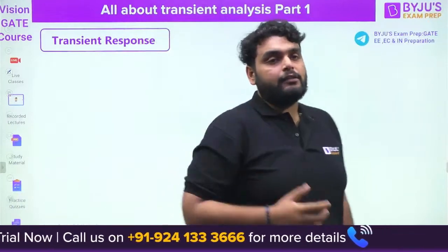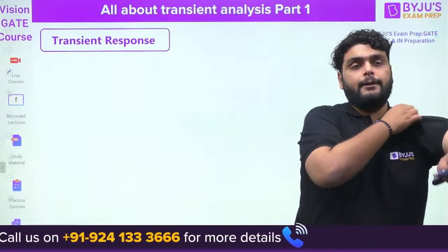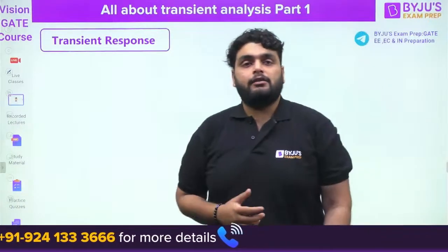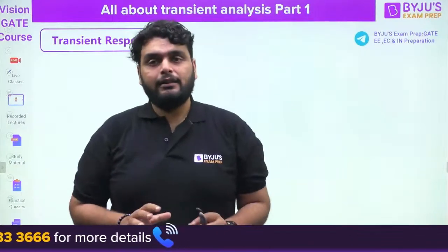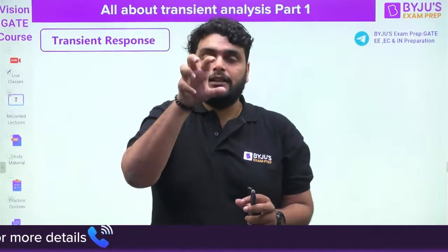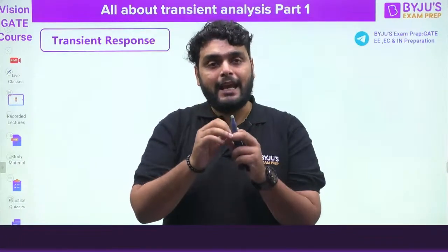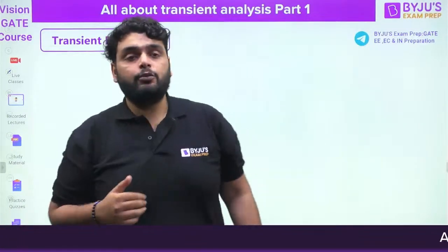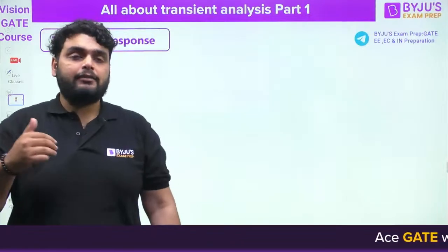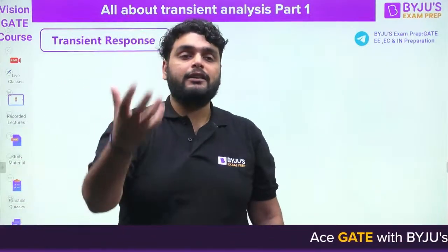So what do you mean by transient? A basic question: what is a transient? What do you mean by transient here? See, transient is nothing but a sudden change that comes in your network, and because of that the network behaves differently compared to the steady state network.